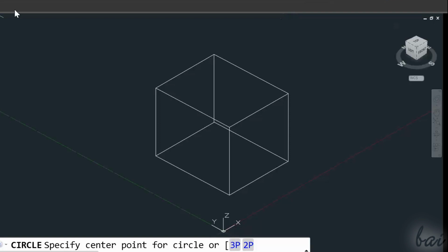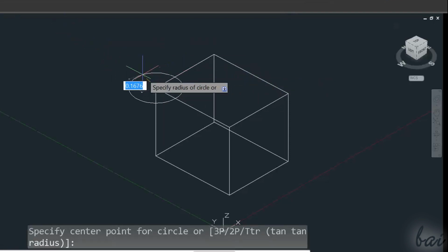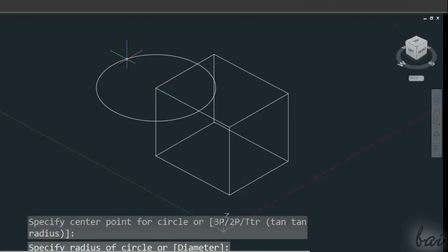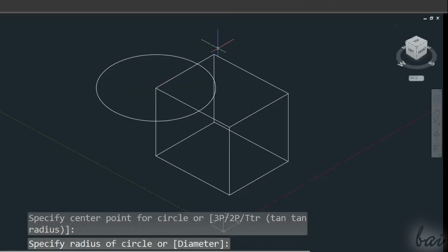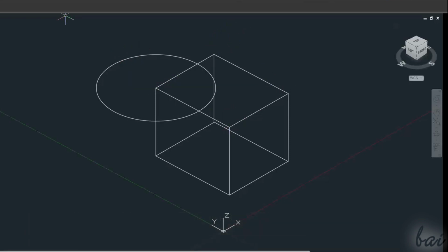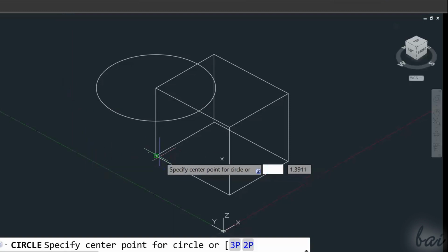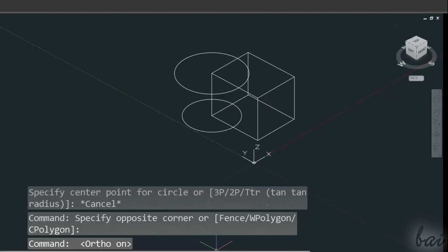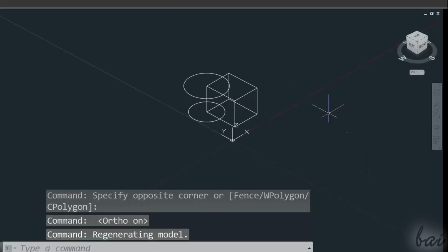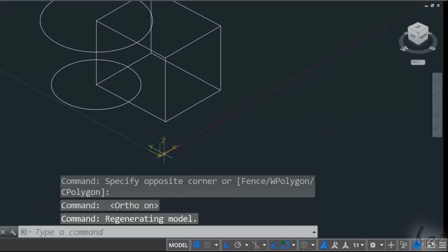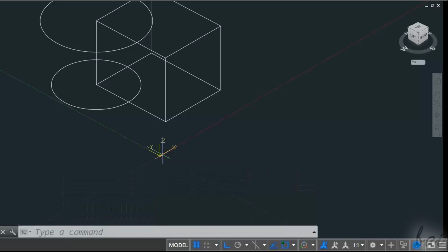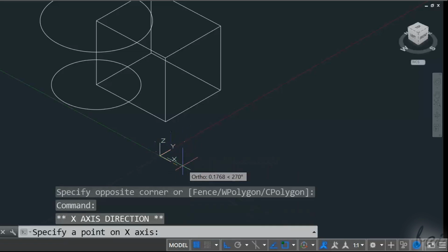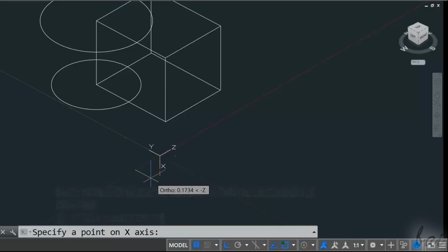However, there are some limitations in using the 2D tools in the Draw section. When you use these, you draw objects on the XY plane, the ground, or any plane parallel to it. If you want to draw through another direction, you need to rotate the XY plane itself. Simply rotate the Cartesian system to do so.